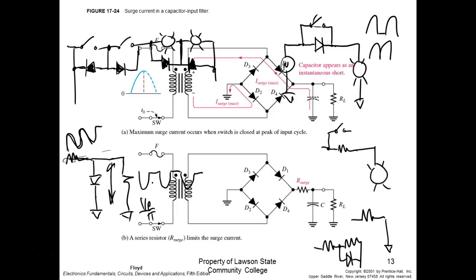Okay, Milton? Or are you still kind of confused? Okay, so I come over here and I put 10 volt peak in or RMS. Over here, that means I would have 5 volts peak. I would take that, divide it by 3.14. Then that would give me my volts DC.